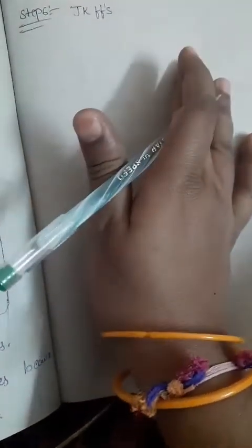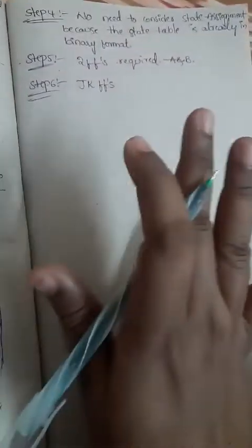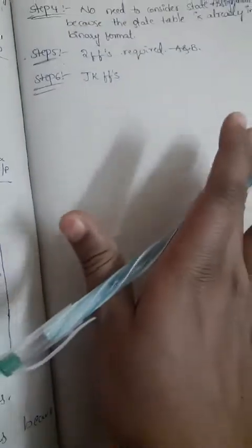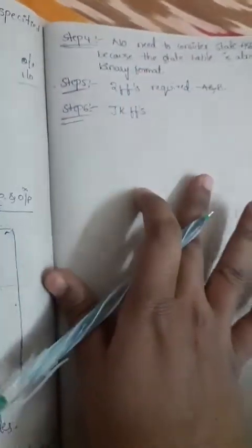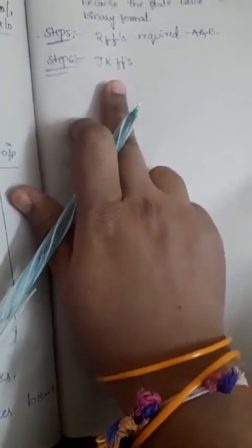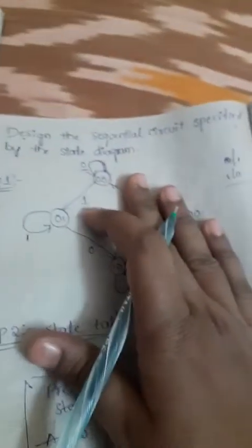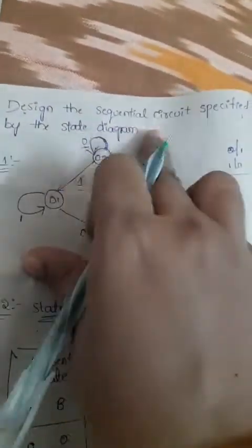Sometimes we use the D flip-flop also. The data flip-flop has reset and set conditions. So we can use JK, D and T. I am considering the JK flip-flop for general applications. If you don't know T and D, you can directly go with JK only. If the problem says to design the sequential circuit specified by the state diagram with the help of a JK flip-flop,